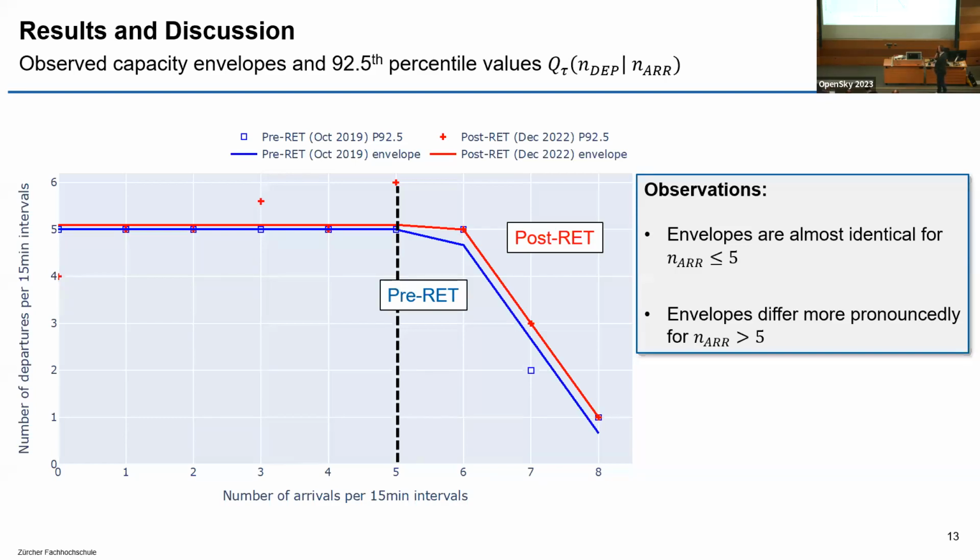Yeah, and I was wondering a little bit because I know from the literature and even from the regulations that you should achieve at least a runway occupancy time of 50 seconds to be close to your capacity value, right? And I want to give the hint as well. There's already a tool provided by the FAA where all the aircraft are in there, and so you can find a good way for the capacity for the position of the rapid exit taxiway.